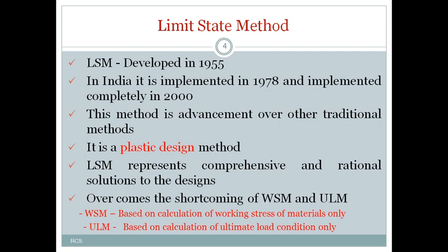Generally this limit state method was developed in 1955, but it was implemented in India partially in 1978, and fully implemented in India in the year 2000. That's why we got the IS code, IS 456-2000, which is completely related to the limit state method of RC structures. And this method is an advancement over the traditional methods like the working stress method and ultimate load method. And it is a plastic design method.